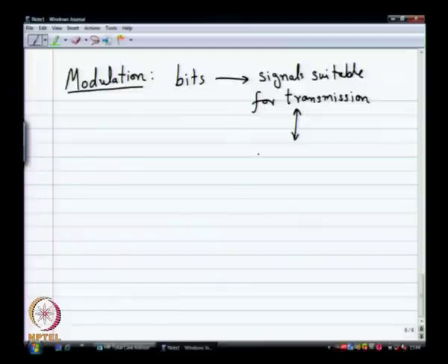You can make an orthonormal basis for the signals, and then express your signals in terms of those basis elements. So you will get a point in the constellation, so to speak, for the signal. Instead of thinking of the whole signal, we will simply think of a point in a constellation, and in fact we will mostly use only a 1-dimensional constellation.